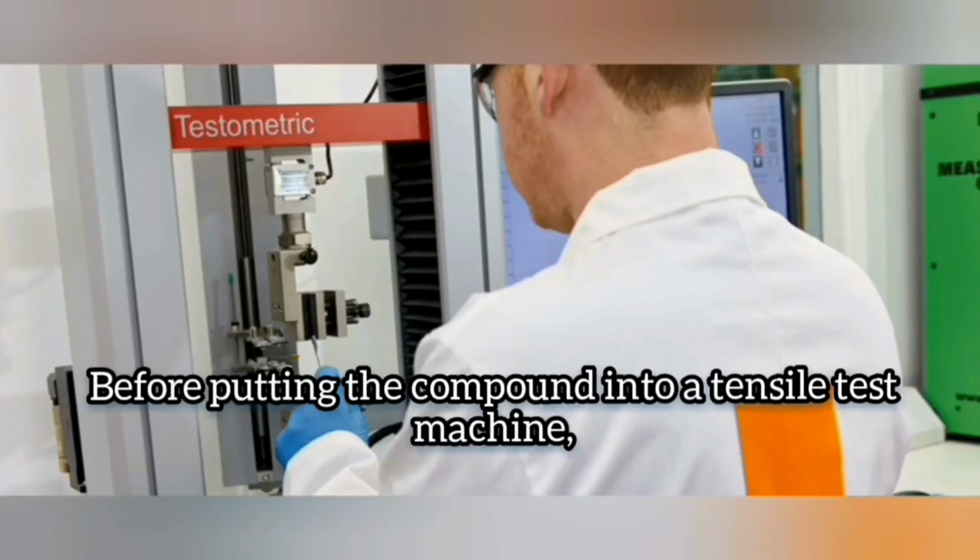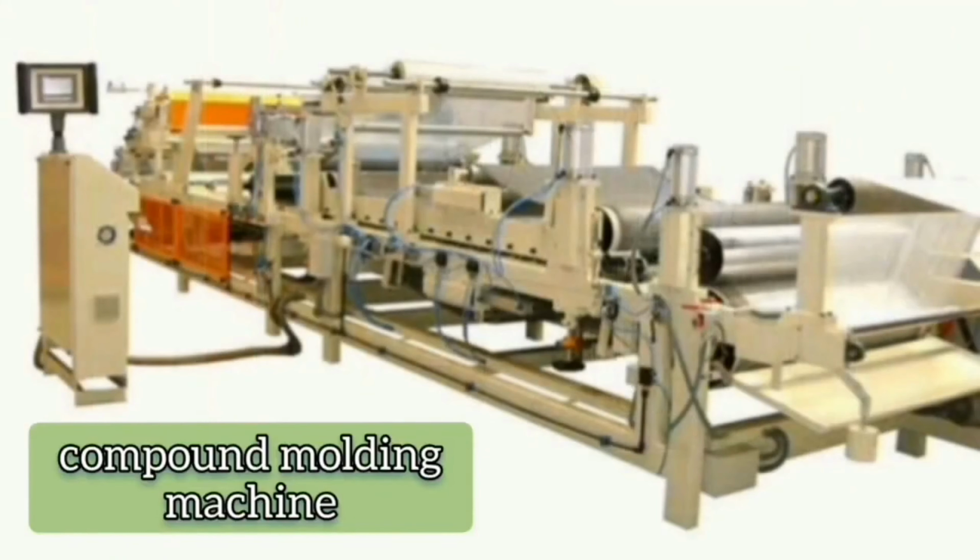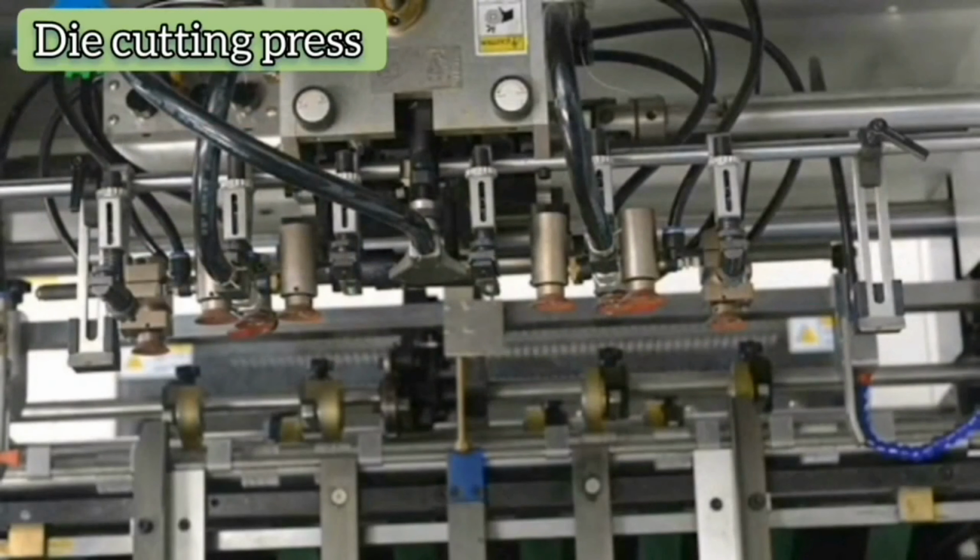Before putting the compound into a tensile test machine, we will have to use our compound molding machine and then the die cutting press to create dumbbells.